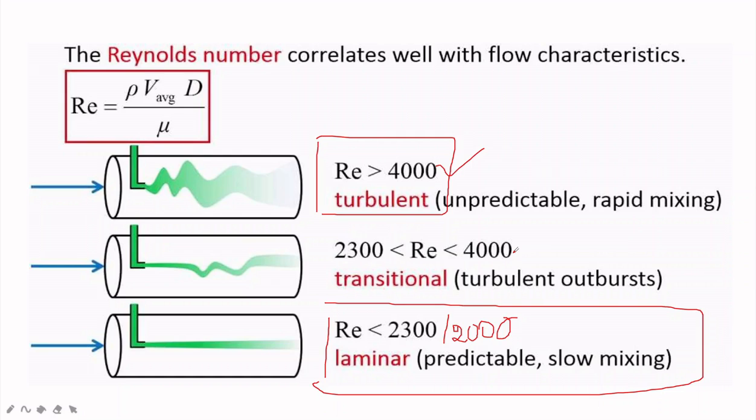So laminar flow, next is turbulent flow. Next, if the number lies between 2000 and 4000, the flow may be transitional. Transitional means it may be turbulent, or it may be laminar, or it may be at a mixing stage, a stage where the laminar flow is changing to turbulent flow. It's a gap when the Reynolds number is between 2000 and 4000. In some textbooks it is given as 2300, and in some it is followed as 2000 only. So this was about the Reynolds number.